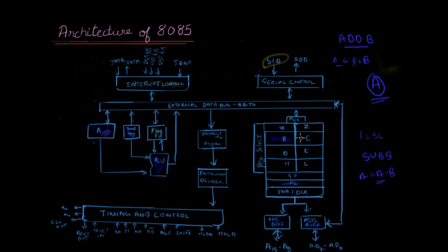We cannot take it as B, D, or H, E, anything else but the order I just spoke about. If you want to take any 8-bit number, we can take the B register, C register, D register, E register, H, or L. No problem. When you want to reference it as 16-bit, we have to make sure that we are taking BC, DE, or HL.